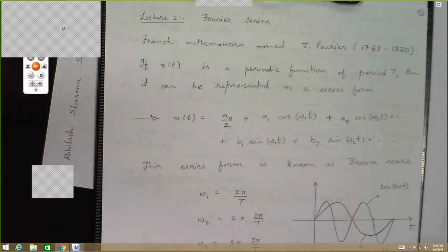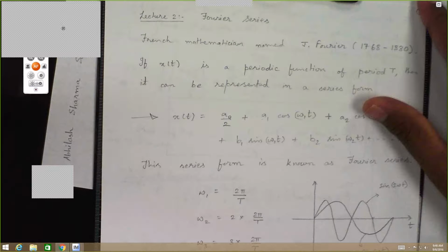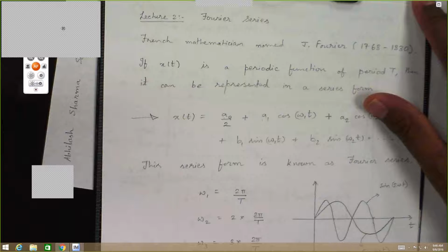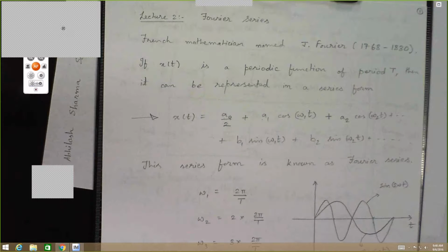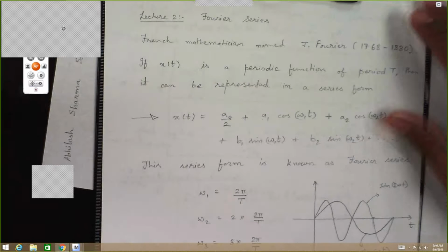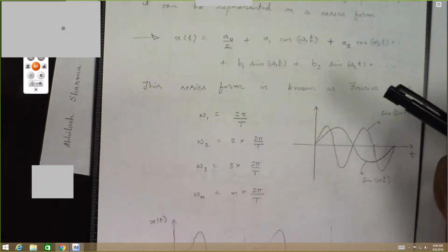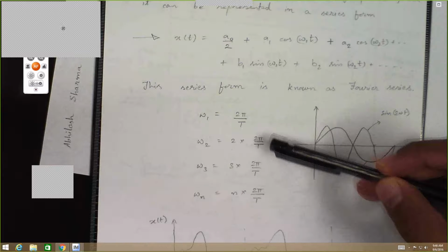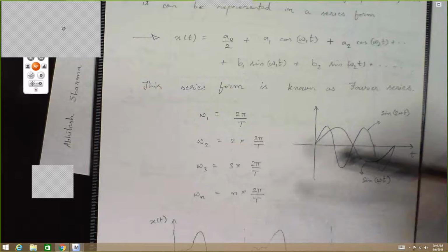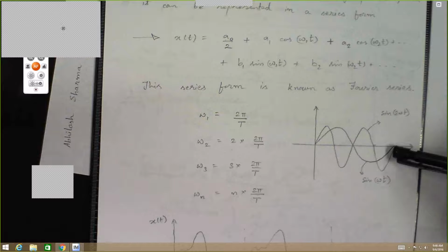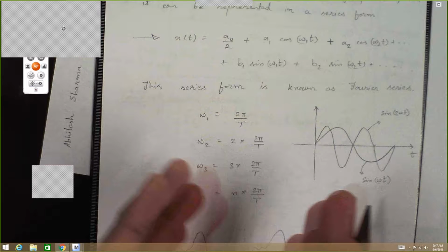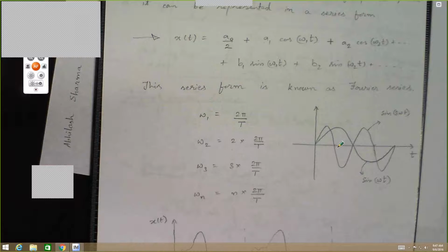Okay, so let's get started then. So we talked about Fourier series, where we were talking about how a signal, if it is periodic, can be expressed as a set of harmonic components with a fundamental period, which is 2 pi over T. And as you go further into higher frequencies, you get higher and higher modes. So we saw how the fundamental frequency is this one, and then we have the higher frequencies, which are also periodic with T, but also actually have a much smaller fundamental period.